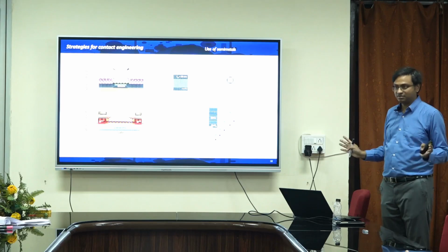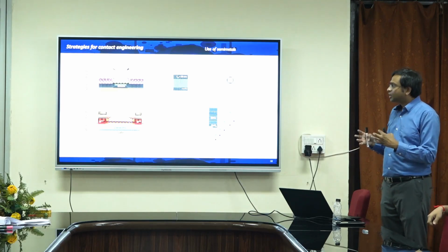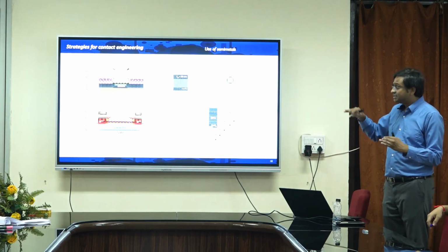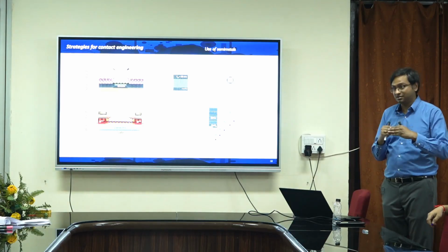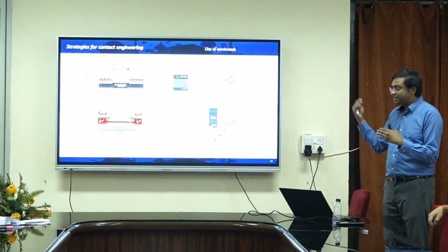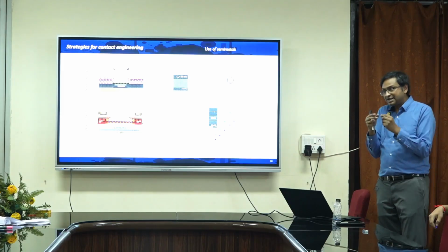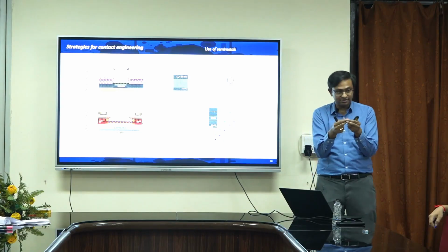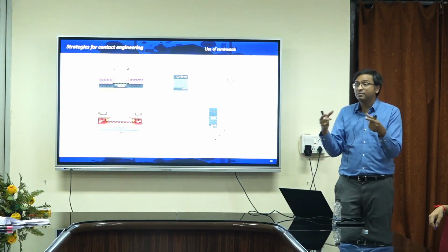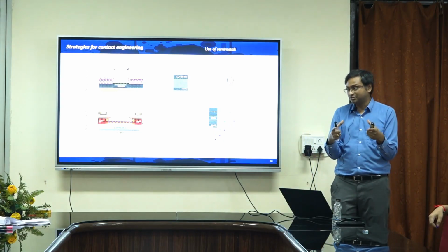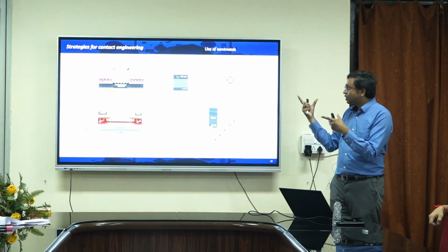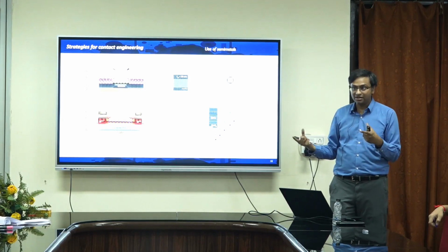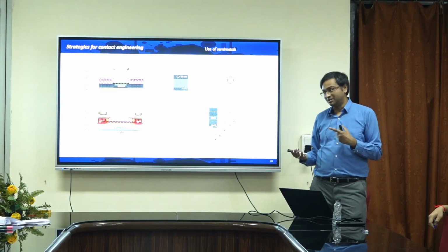But antimony kills it, because, not only that, there is another thing that I did not mention, the epitaxy. What was found is that metals generally have very small grain sizes, so generally we don't talk about the epitaxy of metal. But antimony on MoS2 actually has bigger grain sizes, and that's why we call it a more epitaxial contact, and that also gives lower contact resistance.